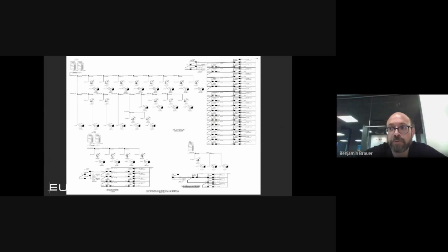In this instance, the rooms were about 8 feet by 12 to 20, depending on the footprint. And in those mechanical rooms, one side was a giant louver for heat exhaust. And in those rooms were what's commonly referred to as the condensing unit, but let's just call it the outdoor unit, which, if you see in the top left corner there, are required to be outdoors, or in an outdoor space that could reject the heat. In some instances we did every other floor. So it was still a mechanical space per floor, but got away from utilizing the entire top floor, for instance, as a mechanical room.